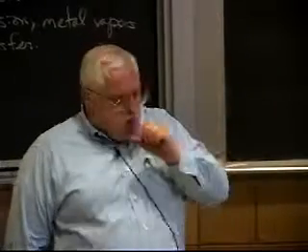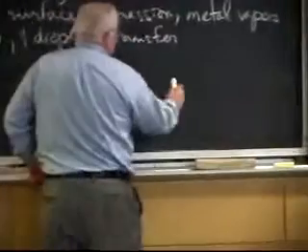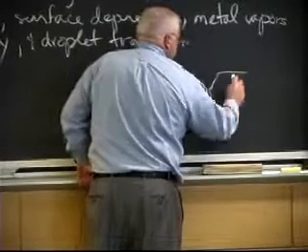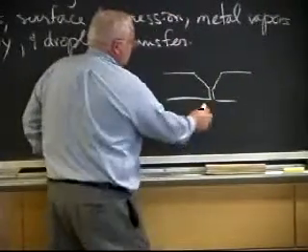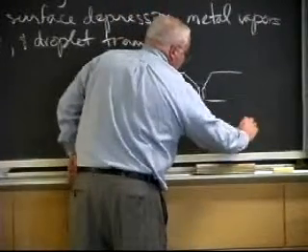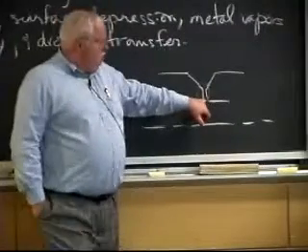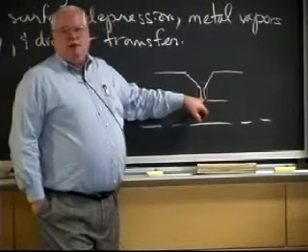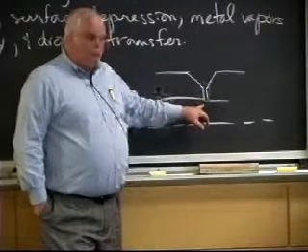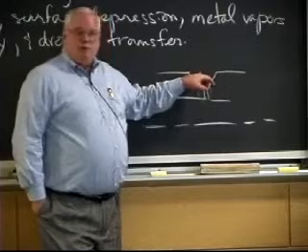Now, another thing, when I talk about surface depression, if you're welding pipe, you might start out with a joint design that looks like this, and you've got to penetrate through here, and since it's pipe, and you've got some center line through here, you can't get to the inside to do anything. So typically on a pipeline like the Alaska pipeline, the root pass will be put in with a stick electrode of a different type than the fill pass up above.